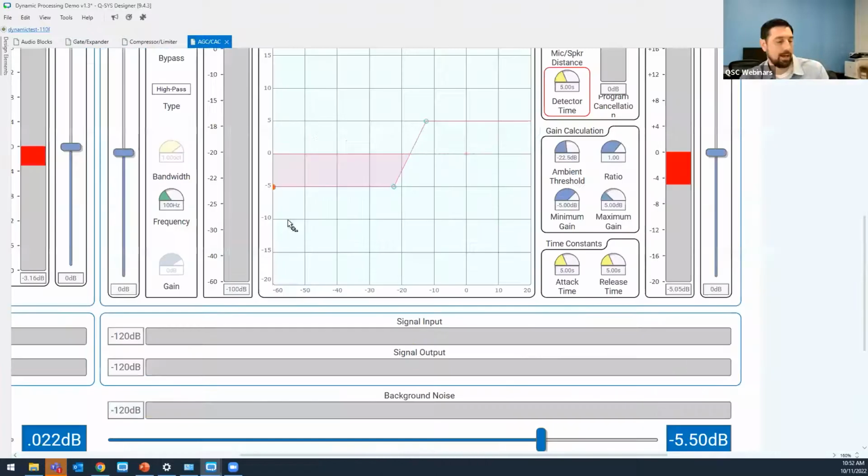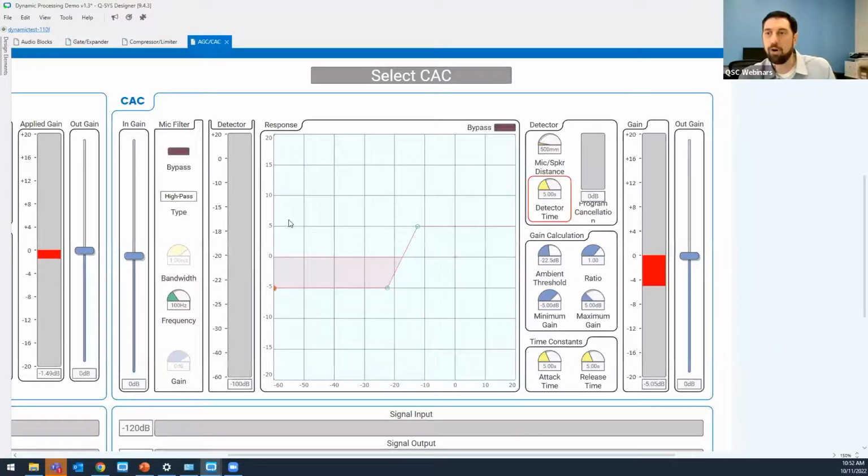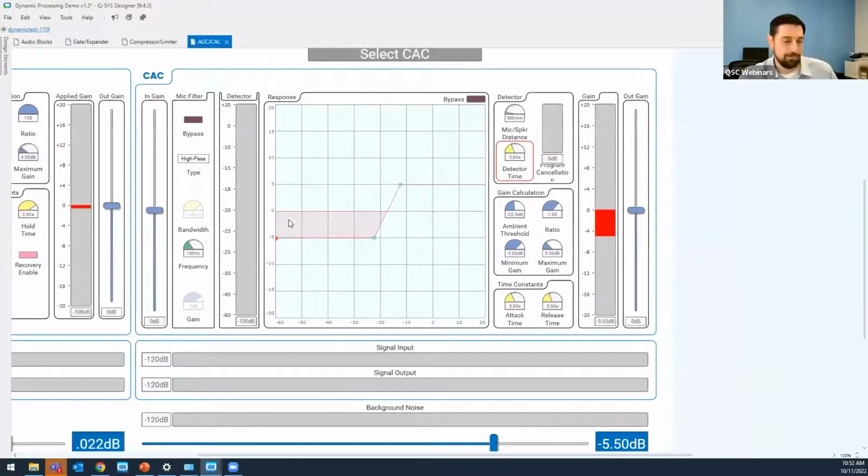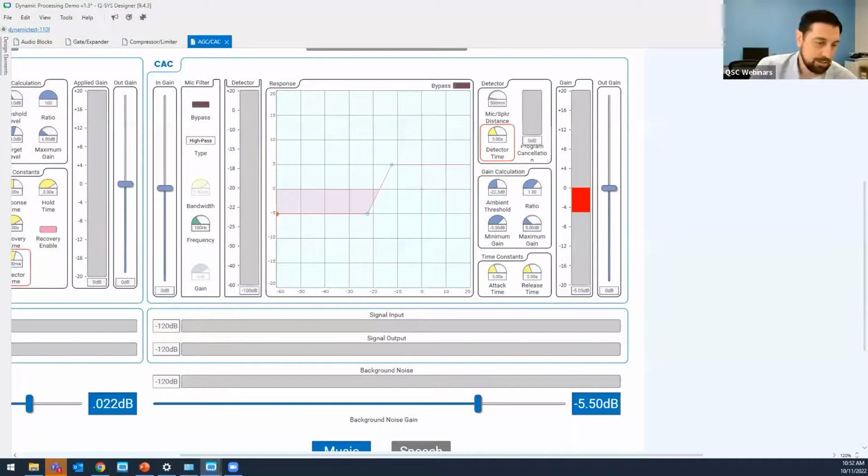The last thing that we're going to talk about today is CAC. This is continuous ambient compensation. For any of my fellow hospitality folks, this is fairly widely used. I used to use these in casino and hotel applications, as well as some sports bar applications. What makes the continuous ambient compensator special is that it has a microphone in the room, and it is sensing background noise, filtering out the music.